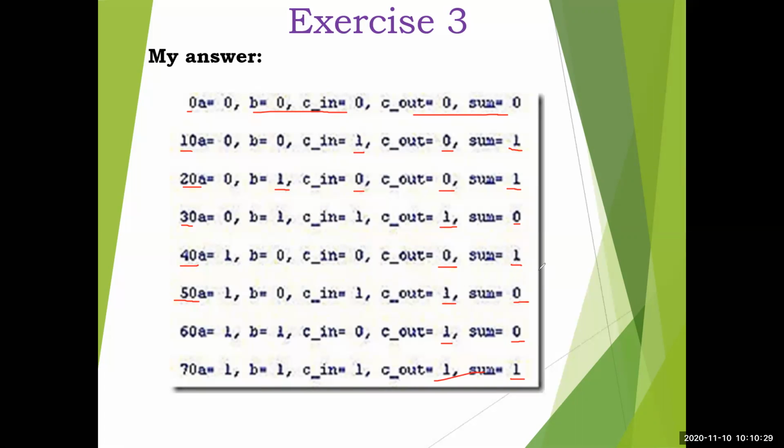Okay, so this is the design. I hope it is clear. The design follows the same procedure: logic symbol, truth table, Boolean expression, gate level diagram, then Verilog description, then stimulus module, and finally the simulation output. Okay, so this is a 7-step procedure. Here they have already given the Boolean expression, so the 3-step procedure is reduced. The symbol, truth table, and logic expression parts are removed. So the remaining 4 you have to do.